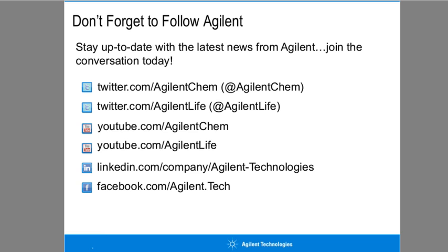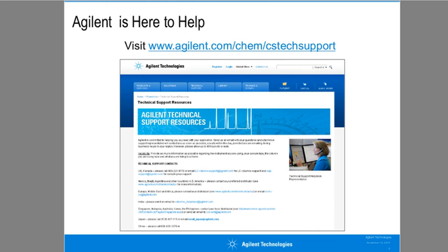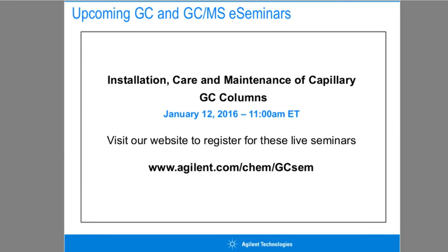We know that, if you have a leak in there, you're going to get a front inlet shutdown. It's going to shut the gas supply off at the back of the GC. A lot of people do worry about hydrogen as a carrier gas, which is a little bit of irony here. A lot of people, or their health and safety folks in particular, worry about 1 or 2 mils a minute of column flow, but they don't worry about 40 mils a minute going at your FID, and that can be more of an issue. If your column breaks, you can get hydrogen back from your FID into your GC oven, which is where everybody kind of freaks. But it's actually really, really difficult from a safety standpoint to get hydrogen built up